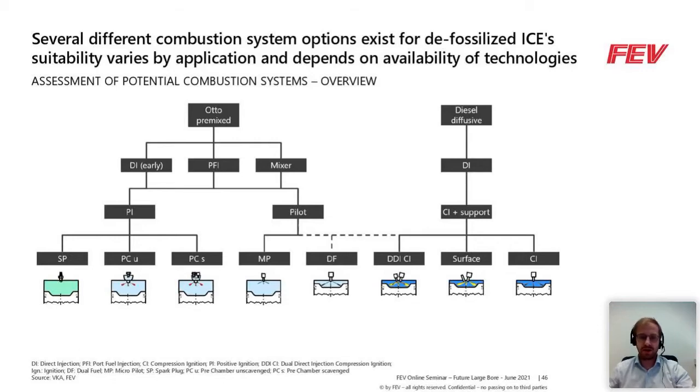This is a pilot diesel assisted combustion system where we use the diesel pilot injection to elevate the temperature and pressure level to then lead to a subsequent compression ignition of the alternative fuel. And last but not least, we also would have the option, which is called here DF. This means in this case a fuel sharing concept where we would mostly maintain the diesel engine and introduce some kind of alternative fuel in the port of the engine.